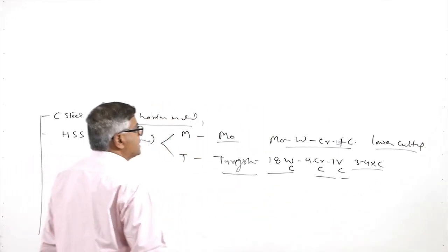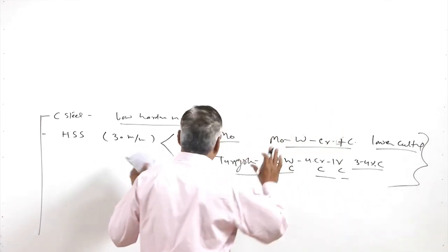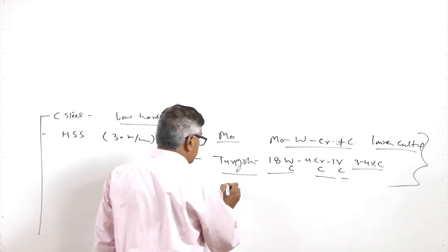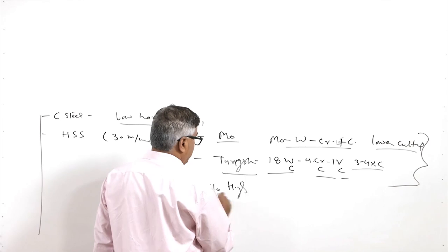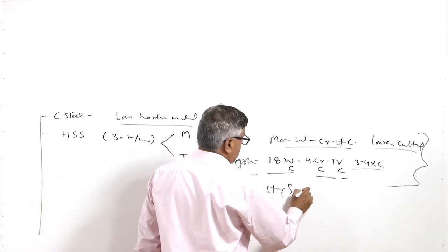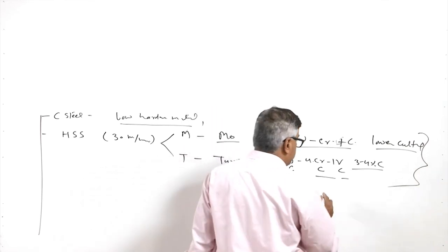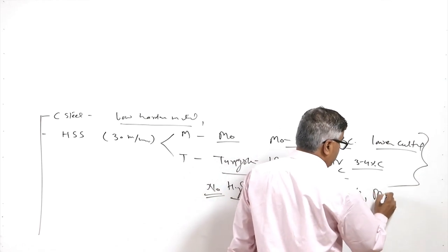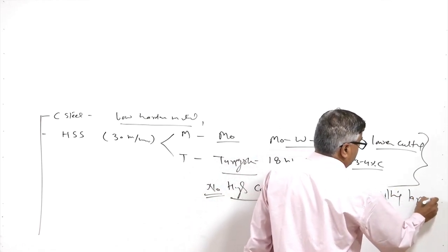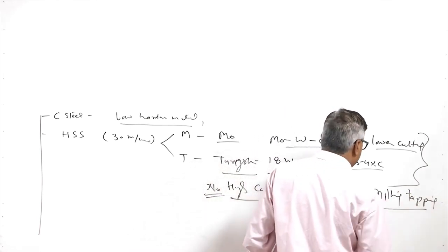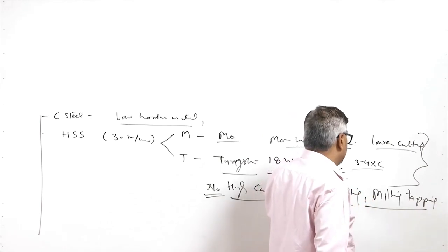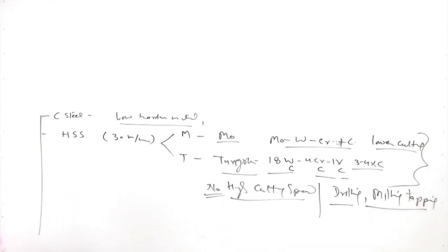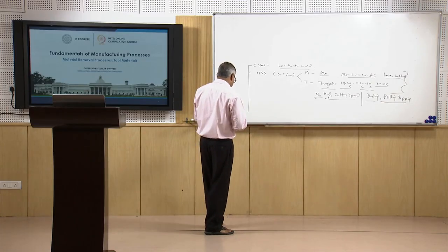high speed steels. These are the tool materials which soften at elevated temperature, and that is why these are not used for high cutting speeds, and that is why these are normally used for low cutting speed operations like drilling, making the tools for drilling, milling, tapping. So, these are the common tools where either cutting is interrupted or the cutting speed is low. So, not much heat is generated, which would cause a rise in temperature, and which would lead to an adverse effect on the tool life.